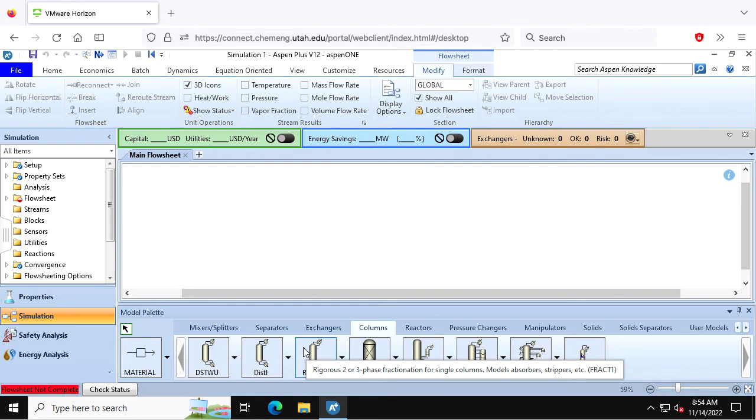So a lot of processes where people are targeting making an alcohol, it's a catalytic process. And you might be targeting propanol, like the C3. But just the way the process works, you'll actually end up with some methanol, some ethanol, some butanol, all these other alcohols. But if you want just the propanol, you have to distill it. And maybe it's a multi-section distillation column, or maybe it's sequential distillation columns. So we'll go through that, not only the performance of them, but the actual design of them.